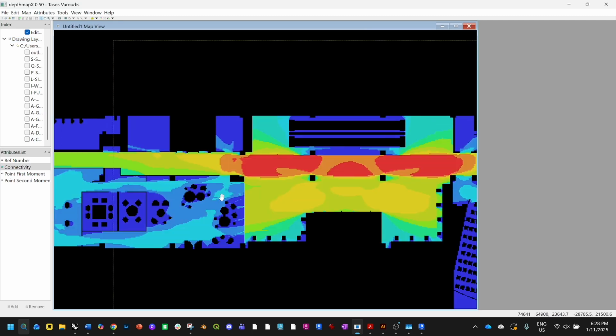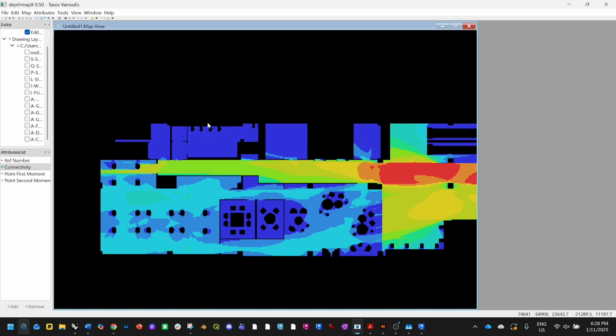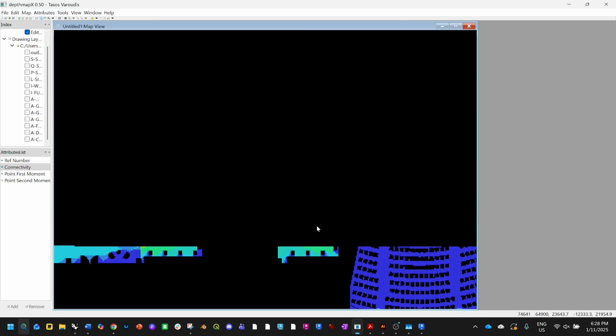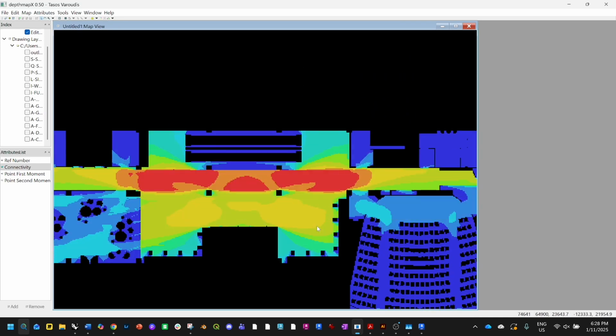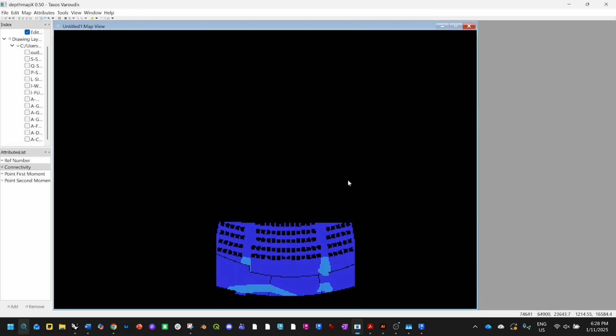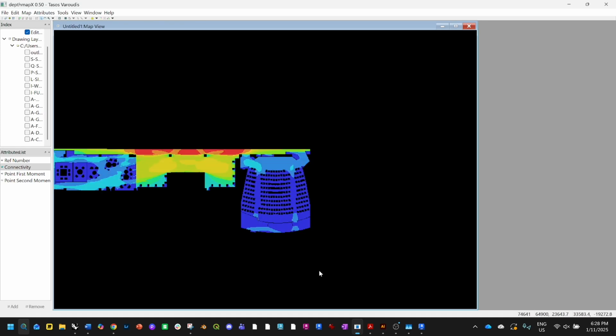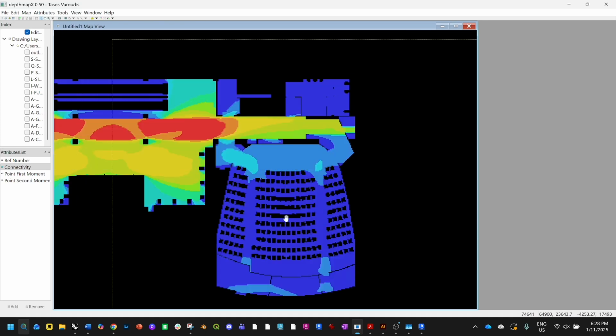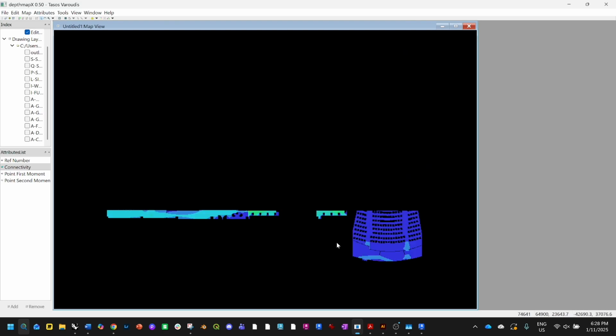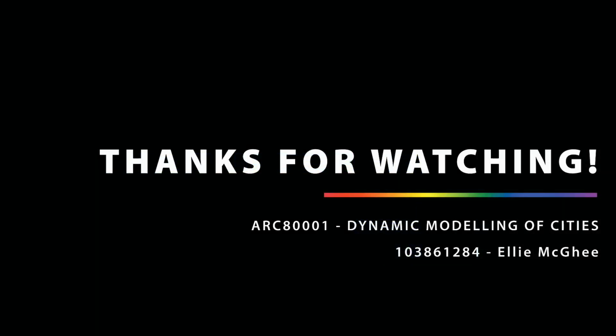So this shows us the blue areas represent spaces with low visibility or low connection, while the red areas are highly visible and connected zones. This makes a lot of sense for this building since I know it personally. The main entry space and hallways are showing as red because they're open and connected, while the rooms appear blue because of all the furniture and walls breaking up the sight lines.